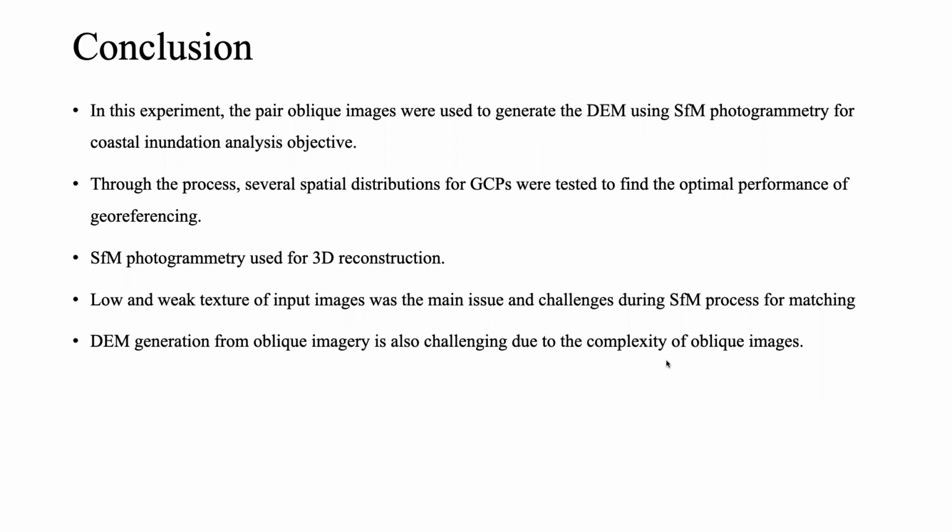Low and weak texture of input images was the main issue and challenge during the SFM process for matching. And DEM generation from oblique imagery is also challenging due to the complexity of oblique images.